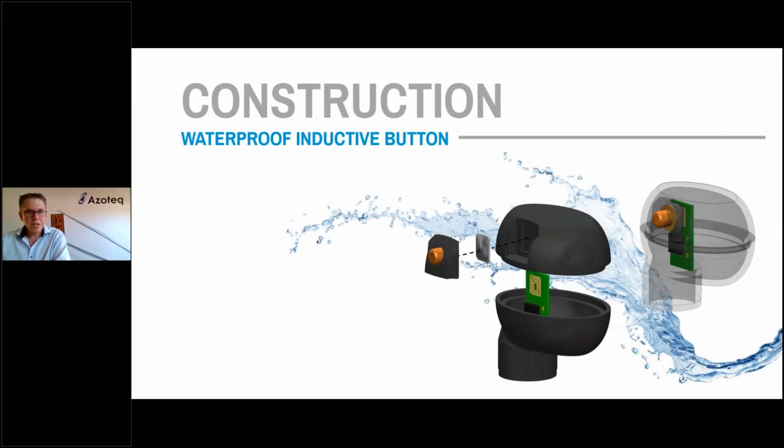We merely measure the instantaneous snap or collapse of the dome that is causing a change of inductance in the electric field, and we can measure that change of inductance. So a pure contactless metal dome is sensed by the coil on the opposite side of the housing.